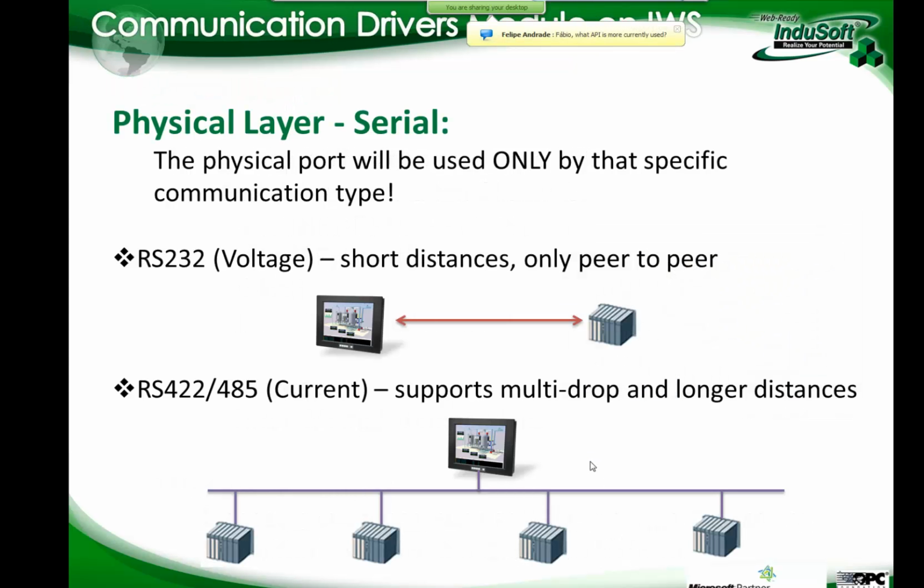There you go. So let's discuss a little bit about the serial channel. When you talk about RS-232, you're going to be point-to-point and short distance. Usually, if you're talking about meters, it's going to be maybe about 30 meters or 90 feet, not more than that. But sometimes that's all you need. But you also have limitations on the communication speed. The max it's going to go is, let's say, 115 kilobits per second. Most of those devices talk 19 to 100, things like this. It's still good depending on what you're going to do.